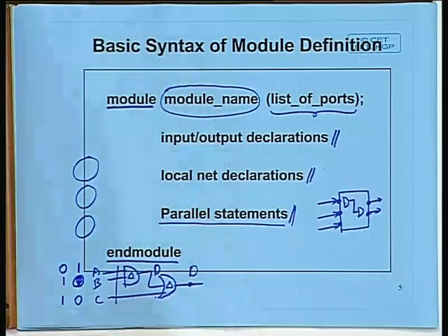What if the delay of the other gate is less than that of the previous one? Delays can be different, because when the simulation is actually carried out, it is an event driven simulation. Depending on the delays of the gates, an event queue is maintained. The gate which is changing state earliest will be at the head of the queue, which is a priority queue. That kind of a list is maintained. We will be talking about this later. Simulation is an important part.